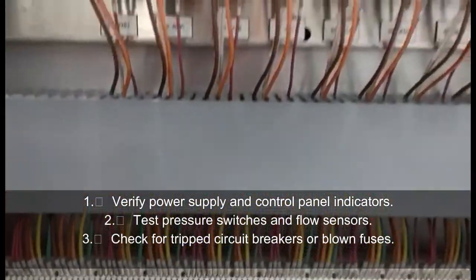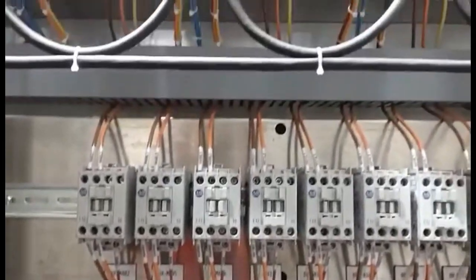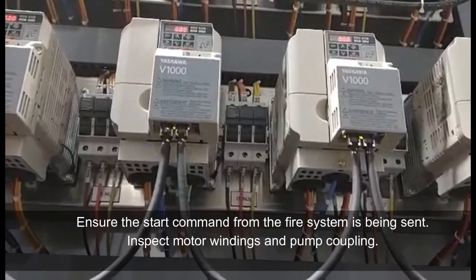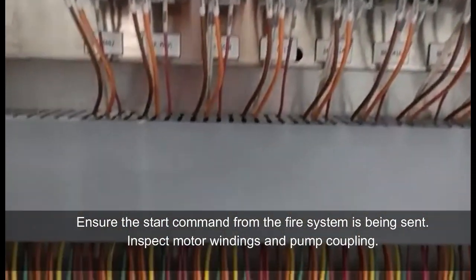Number 3, check for tripped circuit breakers or blown fuses. Number 4, ensure that the start command from the fire system is being sent. Number 5, inspect motor windings and pump coupling.